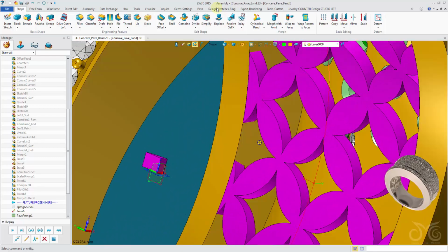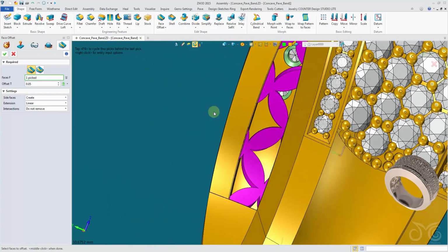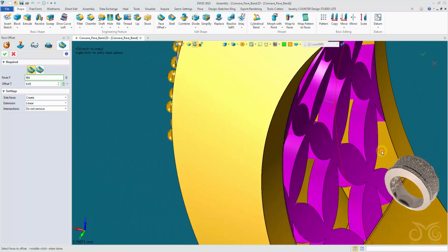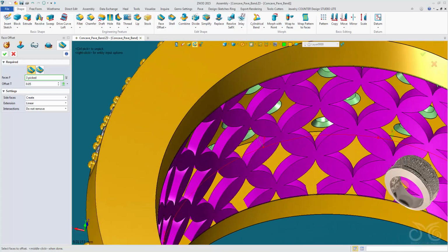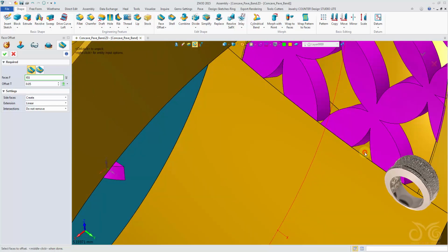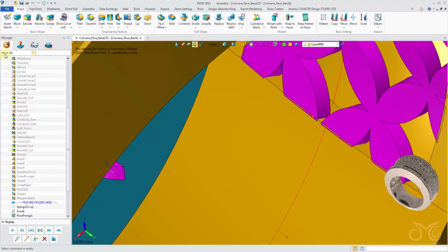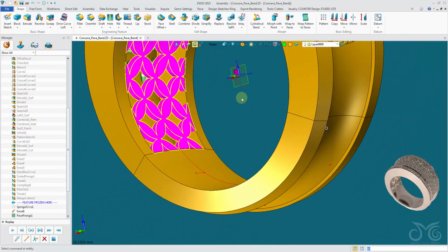We may have to offset these faces just a small amount so that we don't have any issue of coincident faces. Okay, we'll grab the other side. Okay, this is the trouble. You do sometimes experience issues in trying to boolean your parts together. And there are tools or add-ons that you can get that can do a better job of boolean adding.